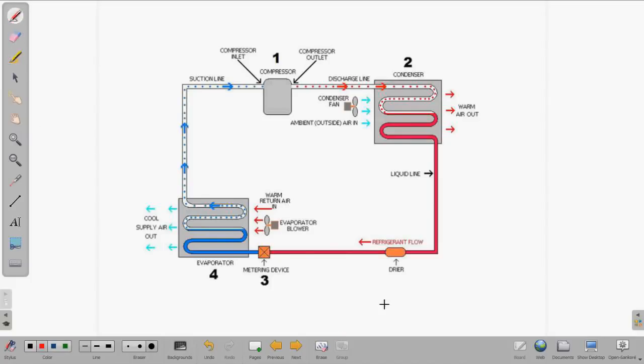All right. So let's go through the refrigeration process. Let's just start right here where we started on our temperature graph, and we'll go all the way through on a refrigeration circuit that's working properly. So this is your outdoor unit, condensing unit right here. As the refrigerant leaves the condensing coil, it is a solid column of liquid, and it should be subcooled liquid so that it's not flashing over,